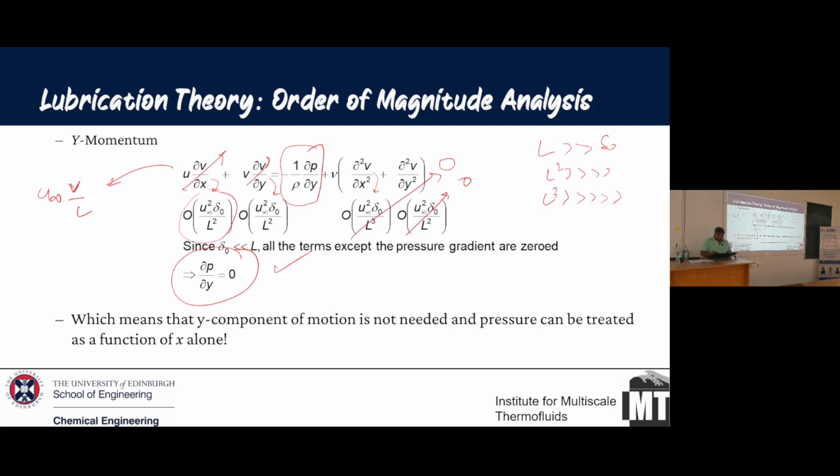Okay, so basically here the meaning of del p by del y equal to 0 is that pressure is constant with respect to y. That means the pressure drop is only in the x direction. It has no implication in the y direction, in the boundary layer.